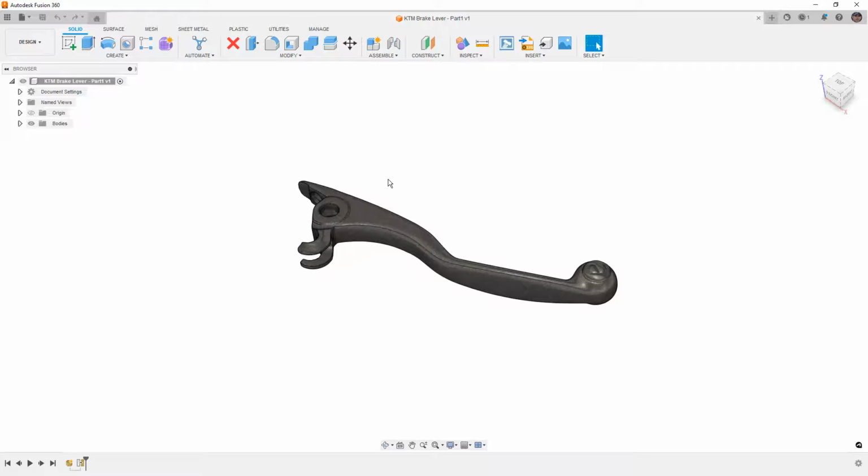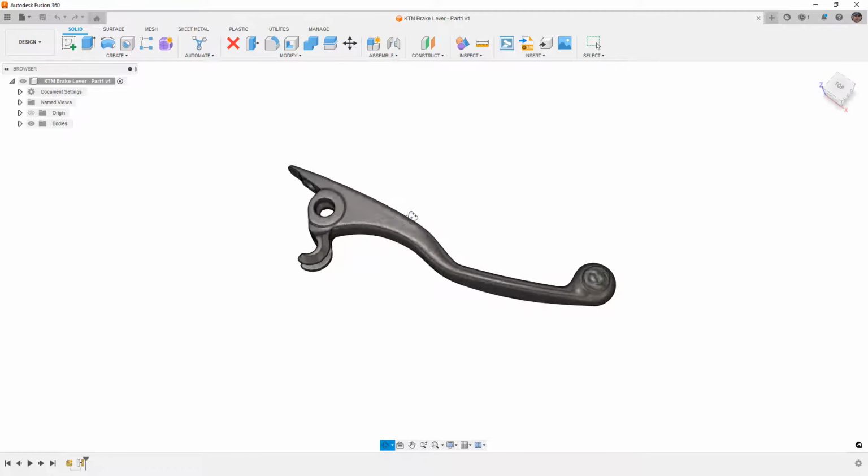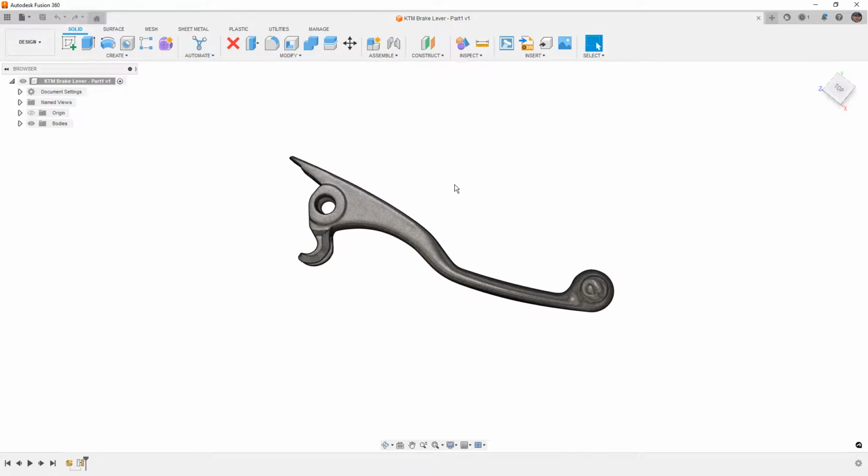So there's also something that we need to make sure that we understand. There are pieces of software out there specifically designed for this. They're meant to take in mesh data and they are meant to help you reverse engineer it. Now, that doesn't mean that you're going to get a parametric feature history based part. It just simply means that you can take that mesh scan data, you can start to build out a BREP or a NURB surface off of it, and then you can look at things like color maps to figure out if you're high or low depending on the original mesh.